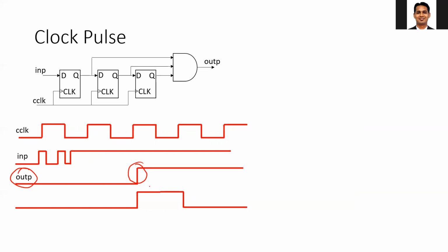But sometimes we want the output in terms of a clock pulse. That means the output will go only once from 0 to 1, and it will remain at 1 for one clock cycle, and then come back to 0. So for every push of a push button, we should get a clock pulse. So how do we modify the previous code to get this circuit?